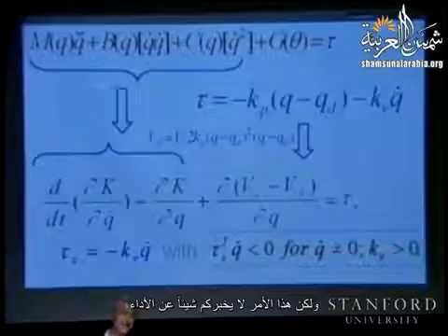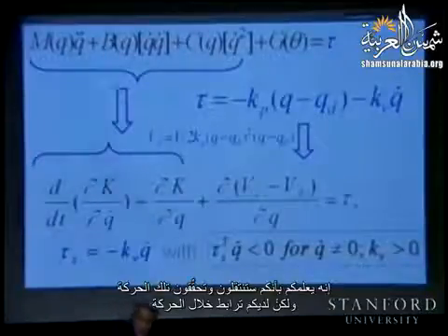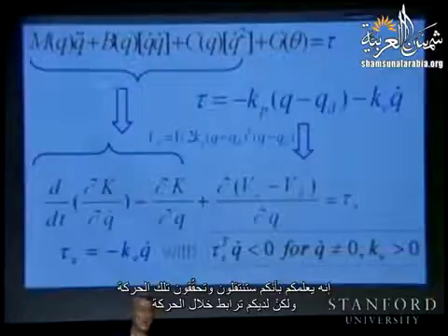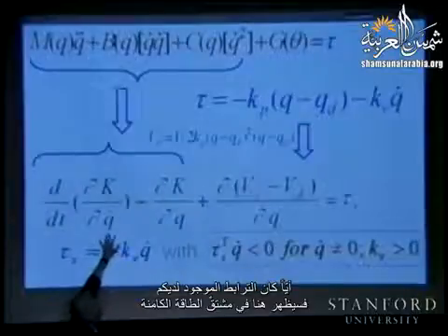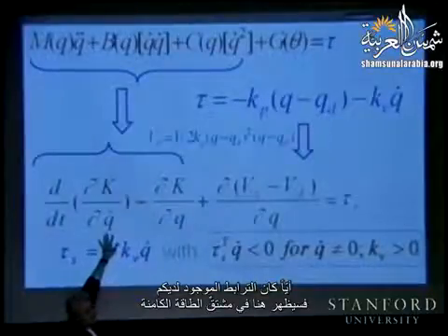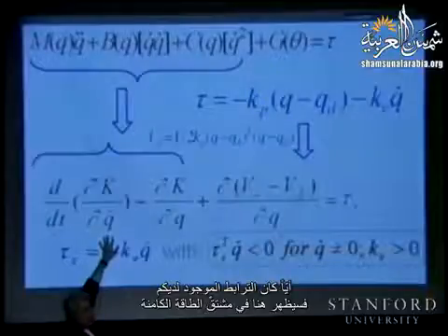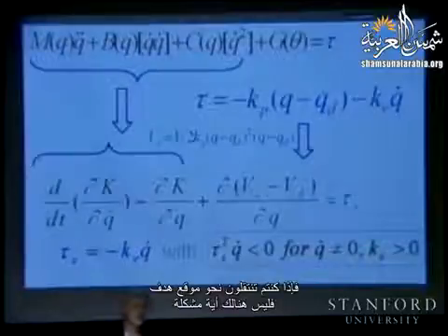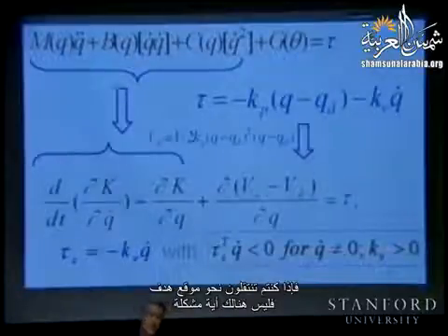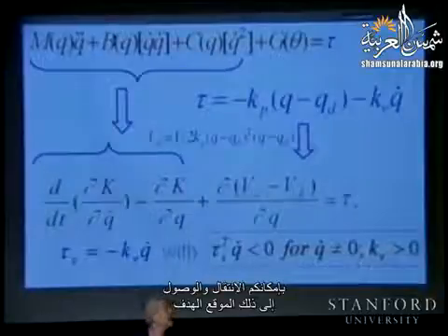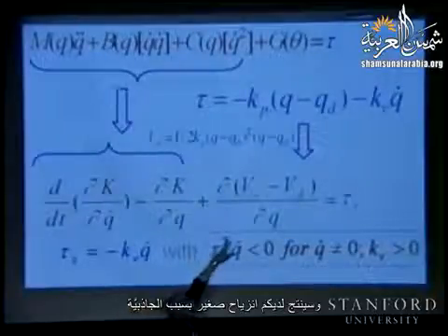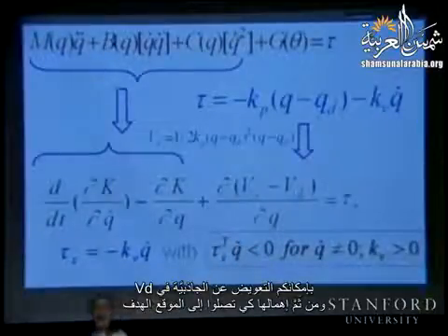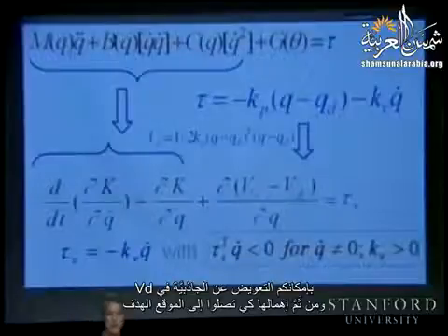But this doesn't tell you anything about the performance. It tells you, yes, you're going to move and reach that configuration, but along the motion you have all the coupling. Whatever coupling you have is going to appear in the kinetic energy derivatives, and that will produce the inertial forces. If you're moving to a goal position, there is no problem. You can move and reach that goal position. You will have a small offset because of the gravity. You can, in fact, put in Vd some compensation of the gravity and take it out, so you can reach that goal position.